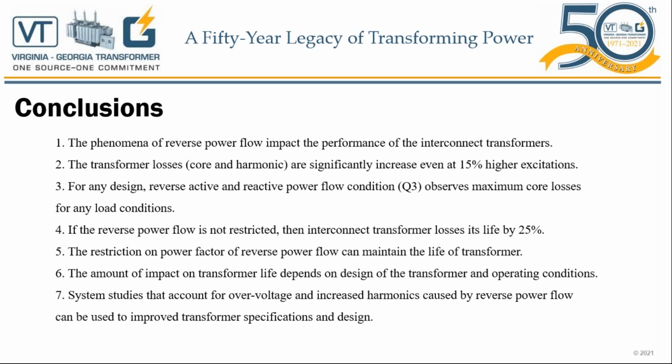Number three, for any design, reverse active and reactive power flow conditions in Q3 observe the maximum core losses for any load condition. Number four, if the reverse power flow is not restricted, then the interconnect transformer loses its life by almost 25%. Number five, the restriction on power factor of reverse power flow can maintain the life of the transformer. Number six, the amount of impact on transformer life depends on the design of the transformer and operating conditions.